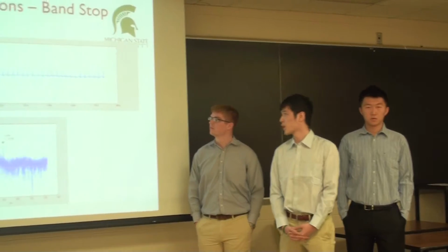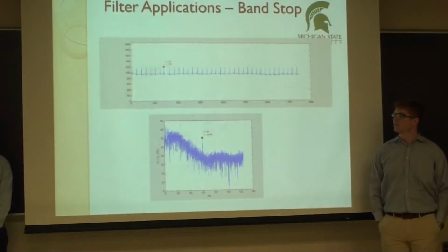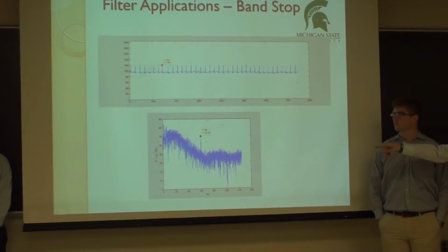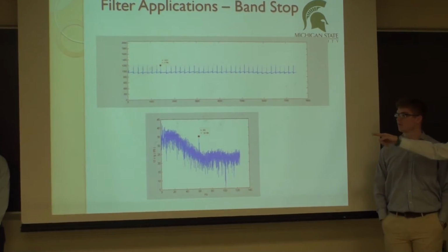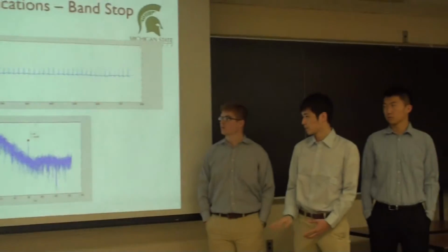The picture above is our ECG signal, and in the second picture you can see at 60 Hertz we got power noise. So in this case, we use MATLAB to do the first simulation. If it works, we can convert to C code and upload and program our microcontroller. You can see from the code we set up the notch frequency at 60 Hertz and the Nyquist frequency, do the sampling rate, and do the calculation.